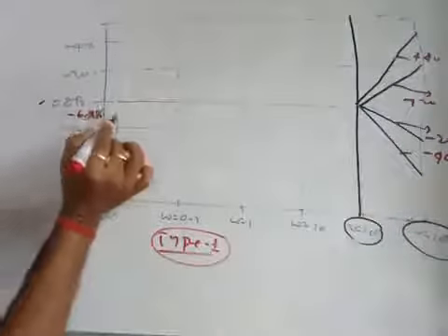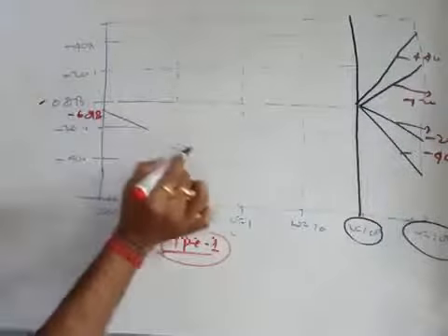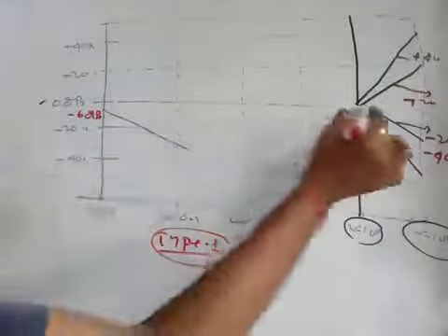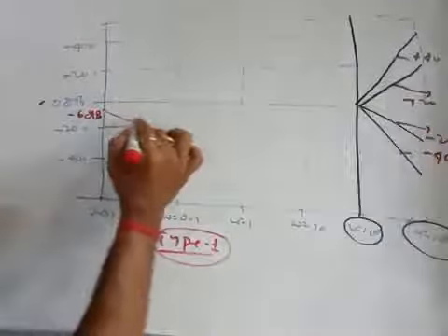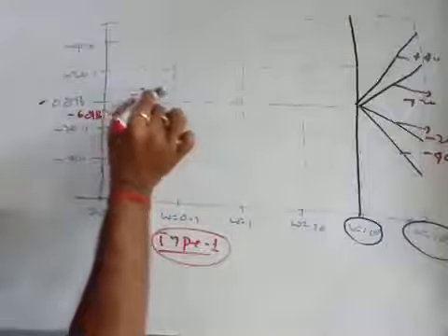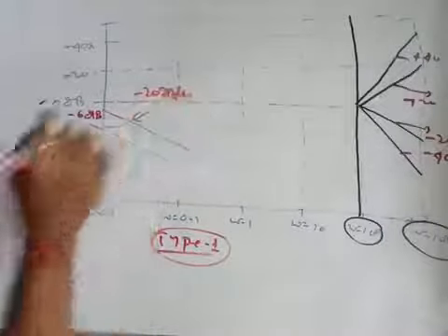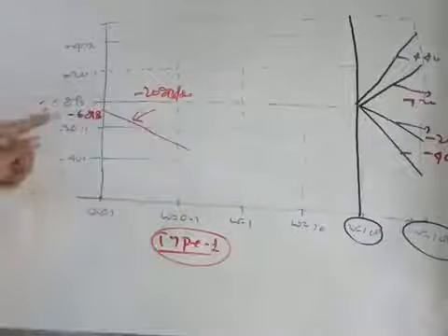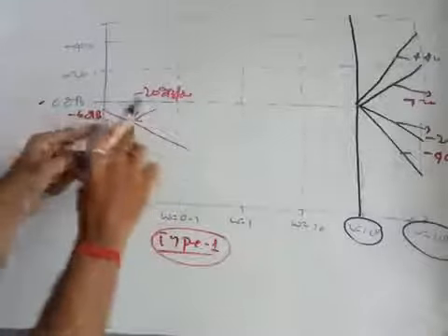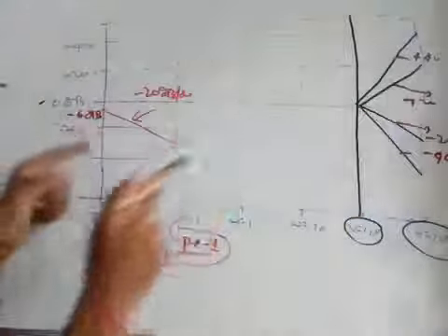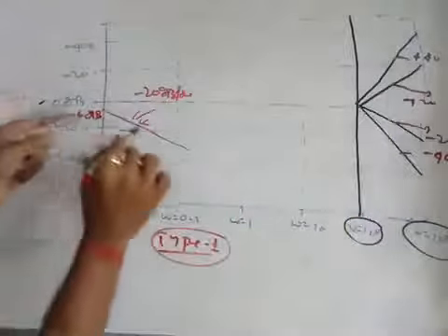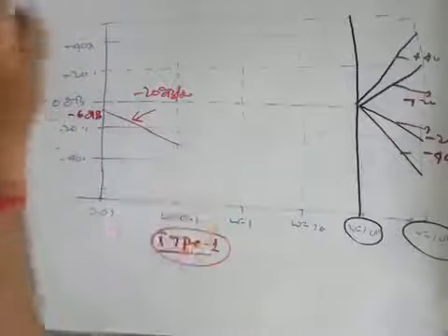So from here you will have to draw a line parallel to this minus 20 dB per decade line. This line and this line have to be made parallel, right? Now up to where these have to move, that is the question.